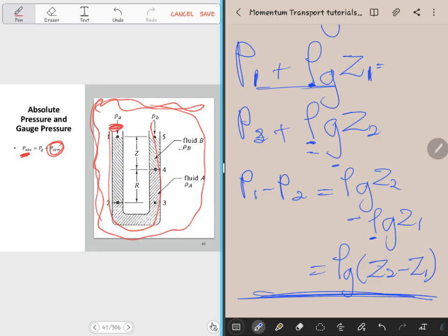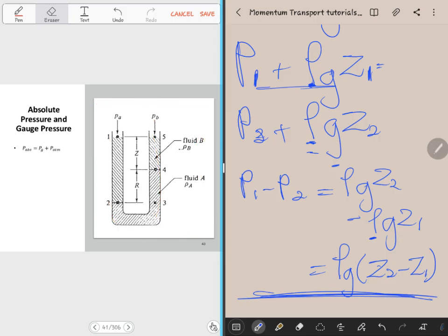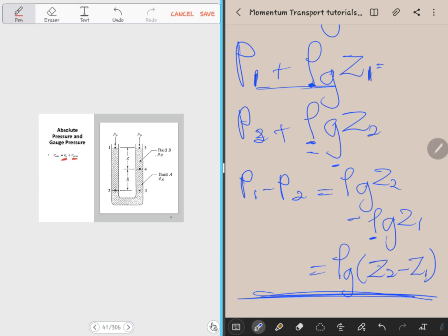And then the outside here is our surrounding. So meaning the atmospheric pressure is acting on the system. So if you have a system like this, an open system, we see that pressure is acting on the system. So generally we'll be dealing with absolute pressure, meaning that any pressure that we find within the system will be the gauge pressure plus atmospheric pressure. But again, it depends on the system that you are talking about. So you look at the system and make the references, and anything that you must add or subtract, you see where it's coming from or where it's going.